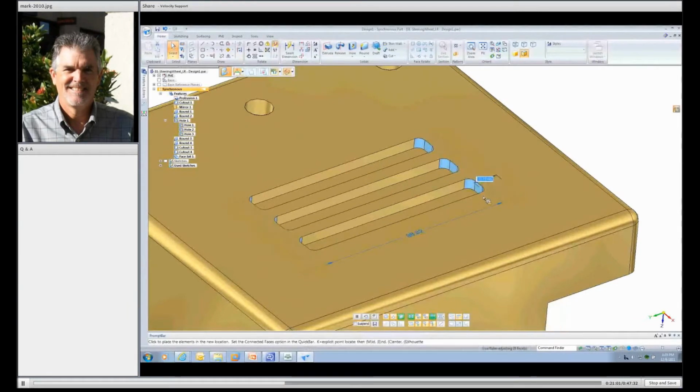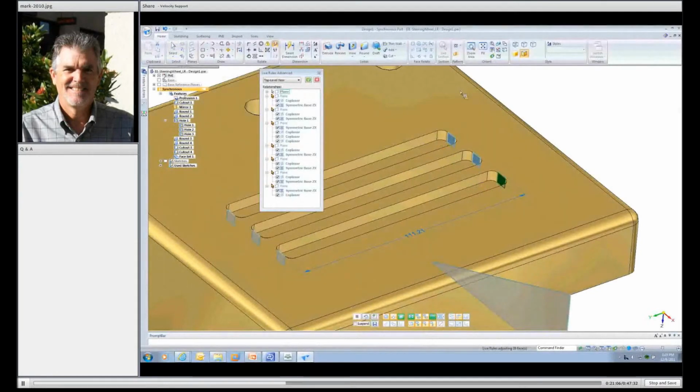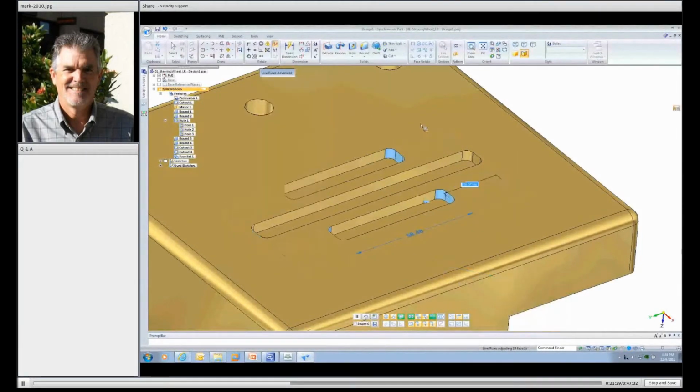And if I go ahead and click to place that, you'll notice now that this slot is no longer coplanar. So if I actually now make a change to this center one, it no longer takes part in those slots. The cool thing here, though, is if I want to reconnect it or remake it coplanar, basically all I have to do is just drag it out, pick up the key point, and reconnect it so that it's at the same width. And then when I go to manipulate, it's right back within the same group because it's now coplanar.